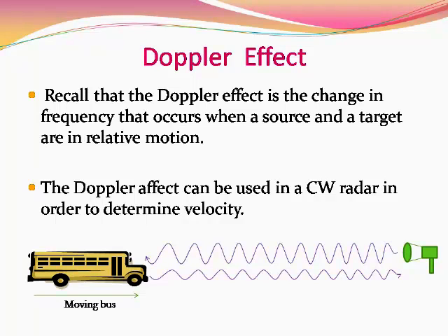Here we are seeing that the source is moving, that is the train, and you are the receiver who is stationary. But it is not necessary that the receiver must be stationary and the source must be moving. The converse can also be the case. Again, in that case also, we are going to see that the Doppler shift takes place. So, putting these two things together, we can say that if either the source or the receiver or both are moving, the received signal is going to have a different frequency compared to the transmitted signal. The picture in this slide indicates that the transmitted signal from the radar is going to have one frequency. The received signal from the target is going to have a different frequency. By looking at the diagram, one can easily come to know about this.